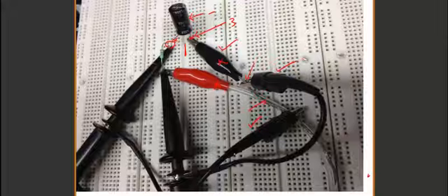And then when you connect the other side of the probe, channel 1 normally should connect to the input. So this is connecting to the input, which is the function generator, the red cable, and channel 2 is monitoring the output, which is actually the voltage across here. So this is the V out.